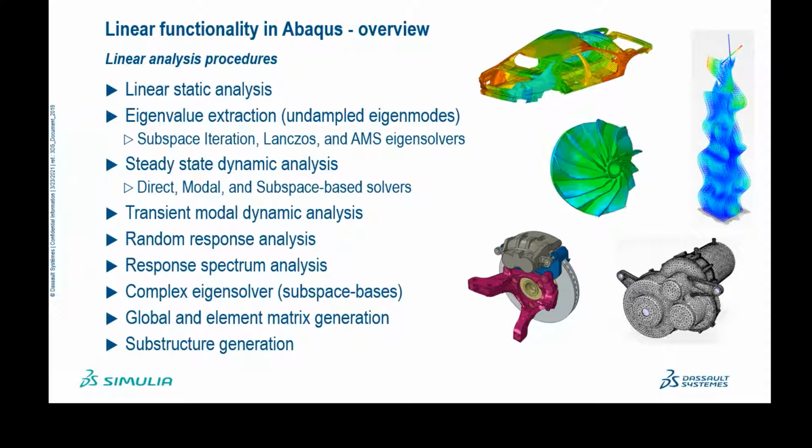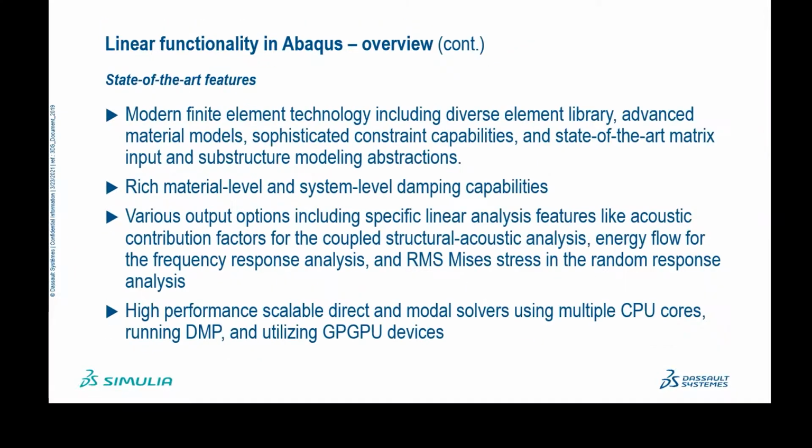Not necessarily purely linear, as opposed to the linear perturbation steps where the solver imposes the linearity condition on all the models built using that type of procedure, which could include the linear elastic static, eigenvalue extraction, steady state, transient, random response analysis, response spectrum, etc.